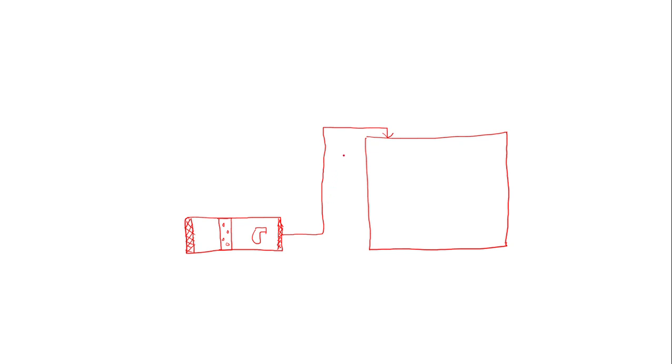This is known as the supply air duct. A duct is a component to carry the warm and cold air to and from the room. So this is the supply air duct. Now as I explained, the warm air needs to be taken back from the room. So for that also I need to have a duct, because I'm keeping the AC unit outside of the room.